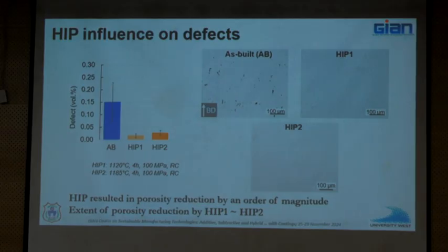Why? Because the more defects we get, the weaker the material is. Even if we think it's just a minor thing and we HIP it, the structure depends on the strength of the material. The more defects, the weaker it is. But you are not going to determine strength in as-built condition. You are going to eventually HIP, right?